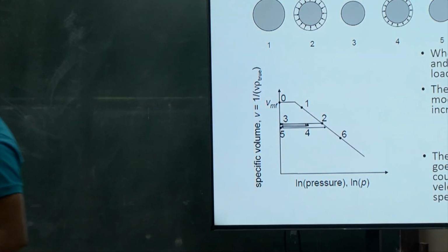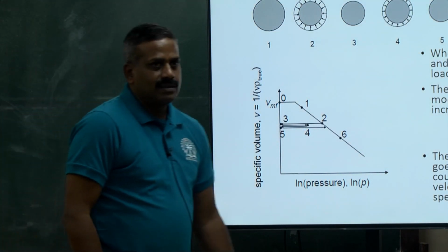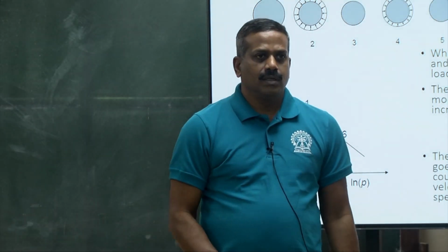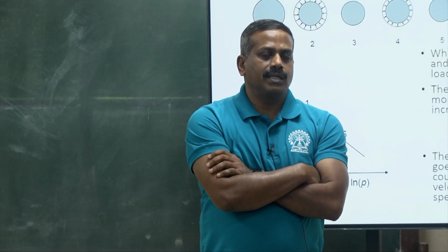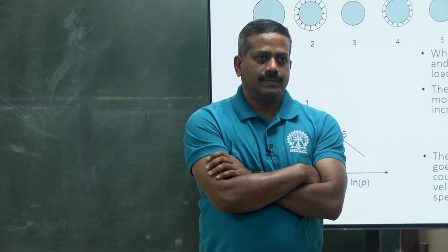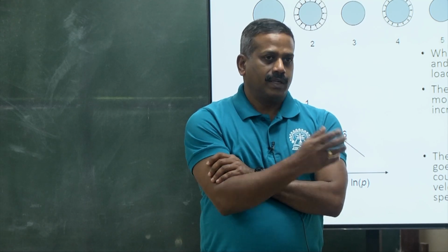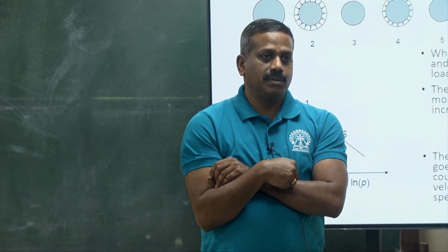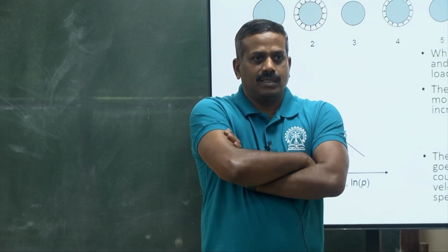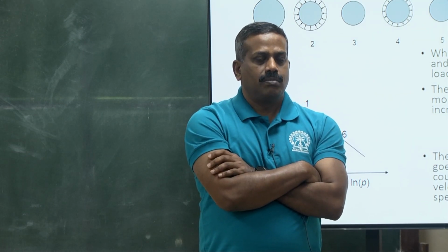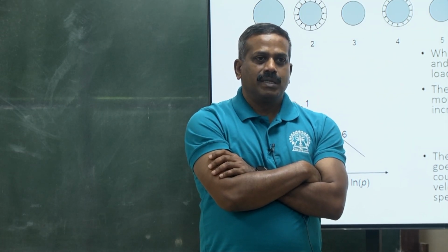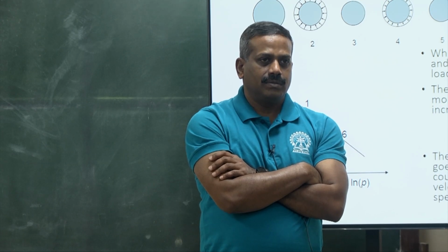Oh, okay. For that, more than aerated bulk density, your particle density will be much better. That will give a cleaner separation. For example, the particle density of fibers will be much different than the particle density of protein. So bulk density may not give a cleaner separation.